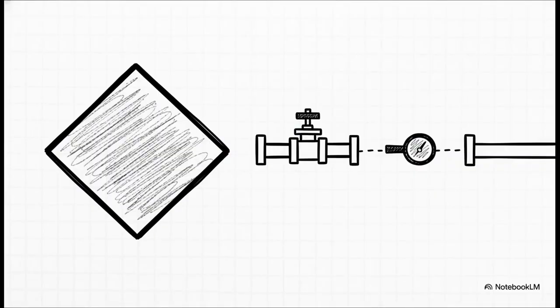But not all sources are that stubborn and independent. Actually, sometimes the source's output relies entirely on what's happening in another part of the network. We call these dependent sources, and you'll usually see them drawn as diamond symbols instead of circles. There are 4 types of these, basically depending on whether they output voltage or current and whether they're controlled by a voltage or current somewhere else. Honestly, just think of them like a smart valve. The flow happening right here is automatically adjusted based on a sensor reading way over there.